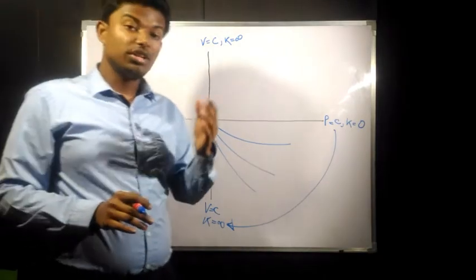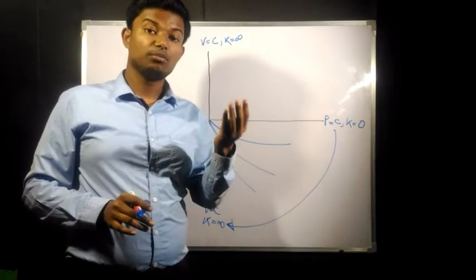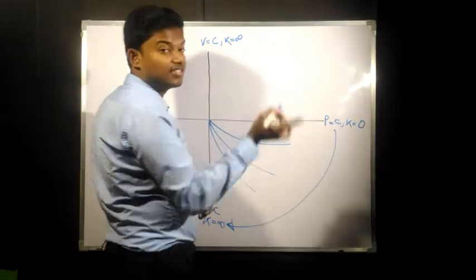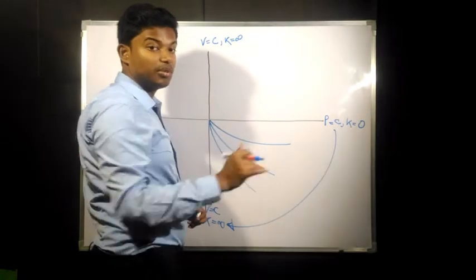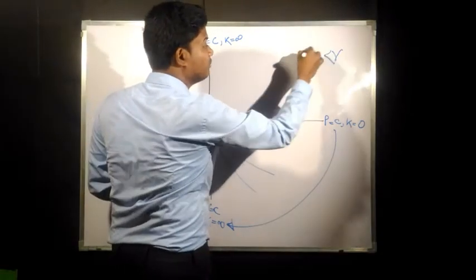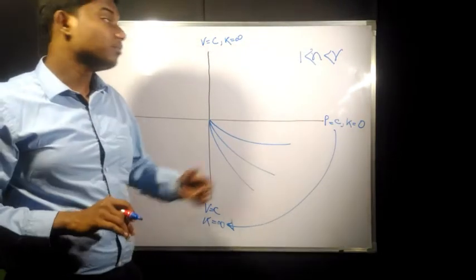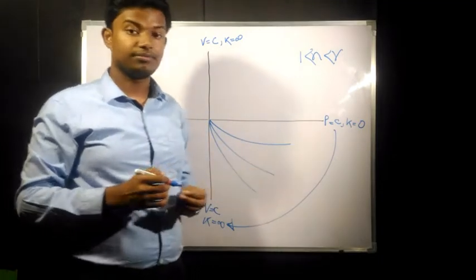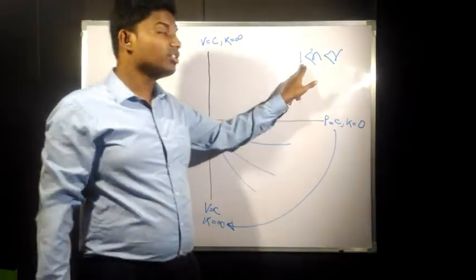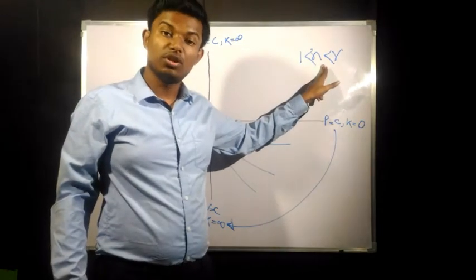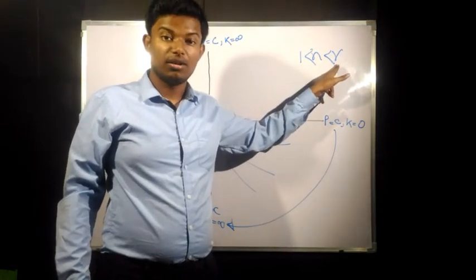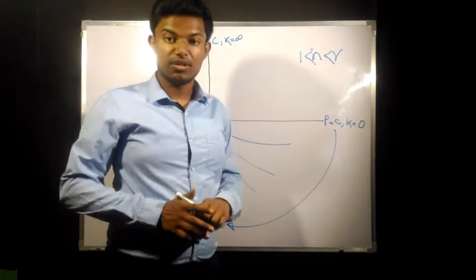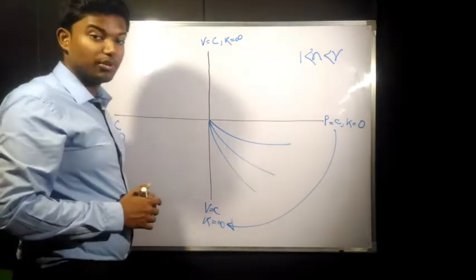Okay, now for polytropic process, what is going to be the polytropic index? If you remember, we discussed it in the last video that for polytropic process n is going to have a value between 1 and gamma. That means n should be greater than 1 and less than gamma. Okay, that means 1 is going to be the smallest, then there will come the polytropic, then there will come the gamma. The gamma value for air is 1.4 and 1 is 1; n is something that will be provided in the question. It will depend upon the polytropic process.